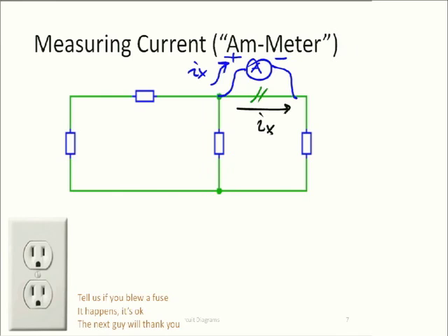So now in this case, the whole current flows through your instrument. That's a little bit of a different situation. So if you were to connect an ammeter, or use your EVM and configure it as an ammeter, usually you have to press a few buttons, so maybe you have to connect your cable to the input. And then you go and connect it to the outlet. What's going to happen? Probably a fuse blows. So which fuse?